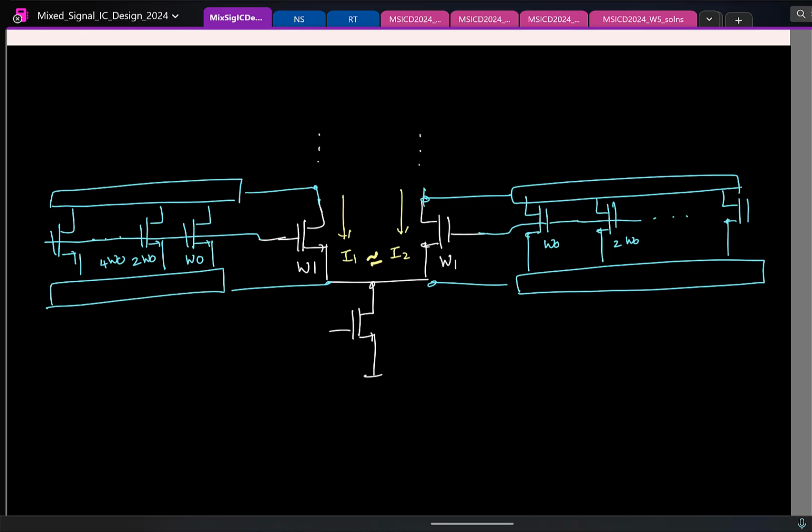Yeah, each and every preamp, and you can actually do this for the latch directly also. For each and every preamp you have to do this, and this can be done on the run using simple digital logic, right? So this is often called calibration.